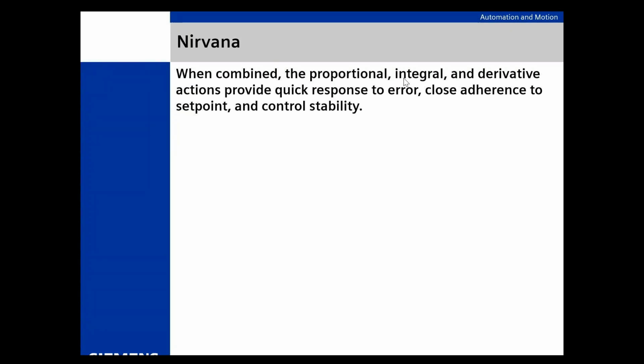If I go into a controller, whether it's a new one or an old one or whatever you got, do yourself a favor and write it down. Get a piece of paper, and let's say I auto-tune, and it gives me a PID. I write it down. Then I'm going to auto-tune it again. Those numbers won't be exactly the same, but they should be relatively the same. It's in the same ballpark.